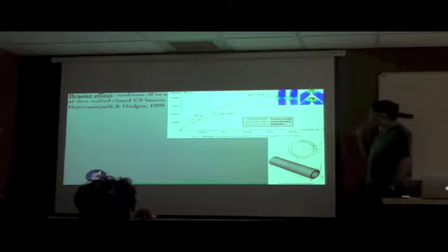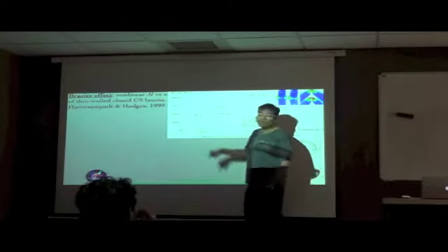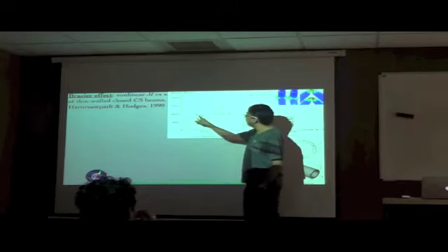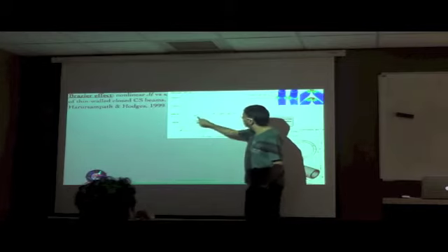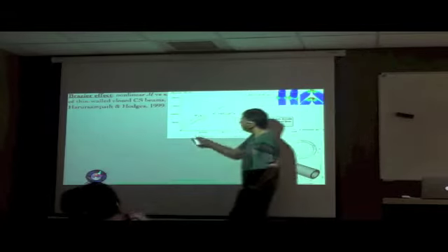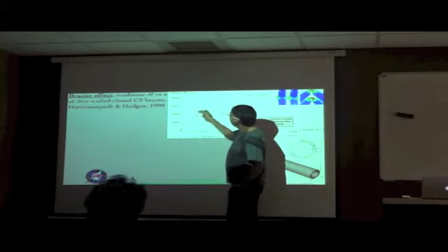But because we are primarily focusing on composites here in this course, I am giving examples related to composites. So, for example, in composites, if the ply layup is just 0 degrees alone, in other words, a unidirectional laminate, this is 0 degrees, 8 plies, and that's the entire thing. And then you see that the bending moment versus curvature initially starts off almost as a straight line, and then it curves around, and you cannot take moments beyond a certain value, and that is the limit moment that we were talking about earlier.